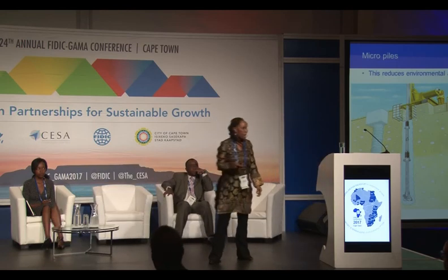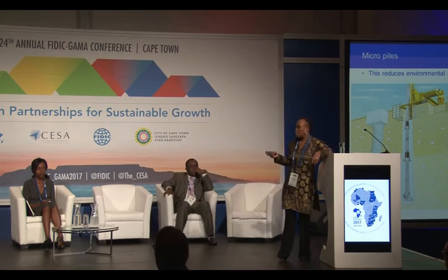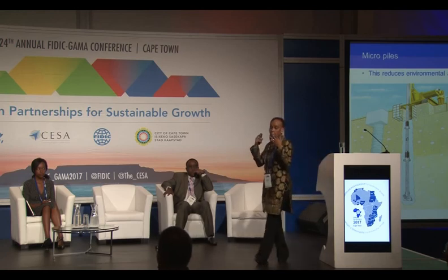And here, micropiles is just a little mention about foundations. And we are finding that, to build capacity, we are needing to deliver projects quicker. And what the micropiles do is they actually cut the time that is taken to do foundations by up to half. They are more expensive, however, time is saved on the actual project delivery.